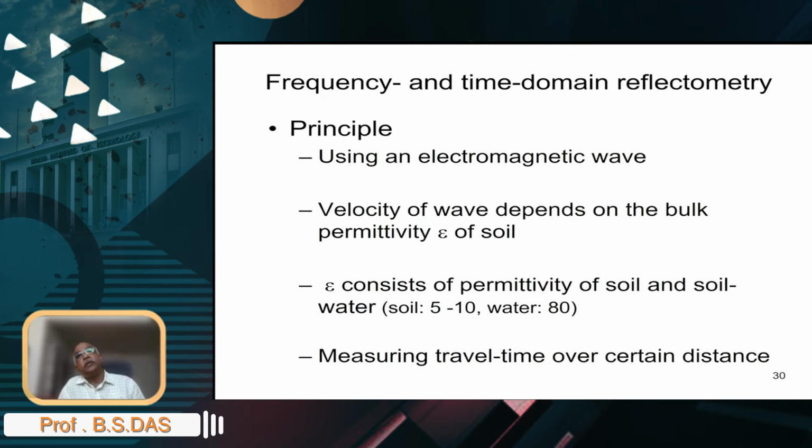you could get the dielectric constant of water, dielectric constant of the soil, dielectric constant of the air, and so you could set up some kind of a dielectric mixing model to back calculate how much water is present from the bulk dielectric constant measurement, right? And so